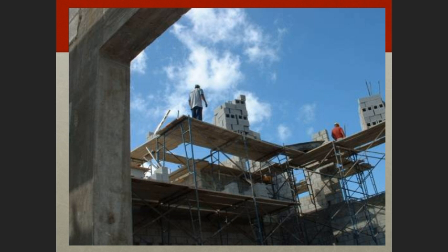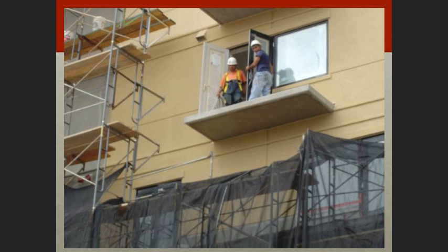Moving on here, we see scaffolding obviously greater than 10 feet. And another hazard that we see here is that the employees have stacked way too many cinder blocks up on the scaffolding. So that's a fall hazard too, because when we overload the capabilities of the scaffolding, we have the potential to have an accident as well. And so let's move on to the last and final picture.